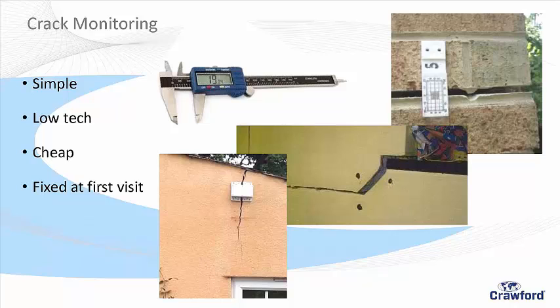It's only one-dimensional. This is probably better. They're called digital calipers on what they call DEMEC studs. Now you're measuring movements in two directions and very, very accurately, to the 100th of a millimetre. We sometimes use these remote devices as well. These are electrosensor devices, and we've got about 50 of these deployed out there. Still tested and corroborated, but it's good.